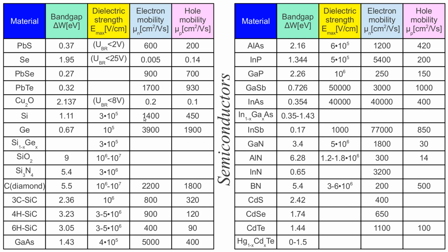Well, but with silicon, this difference between mobility of electrons and holes is not as large as it is in III-V semiconductors. In III-V semiconductors, like gallium nitride, which can be used for very high frequency, very high power transistors, electron mobility is okay, but hole mobility is very low. So we are not going to make p-channel. It does not make sense to make p-channel transistors out of gallium nitride. The same for other semiconductors.